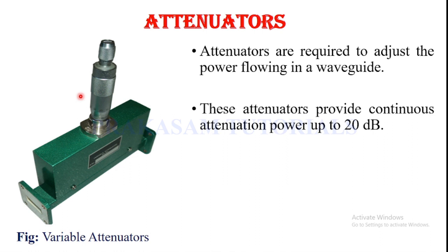For a perfect match, sometimes it is required that the microwave power in a waveguide be absorbed completely without any reflection and be insensitive to frequency. For this reason, we can use variable attenuators. Attenuators are commonly used for measuring the power gain or power loss in decibels, and for providing isolation between instruments.